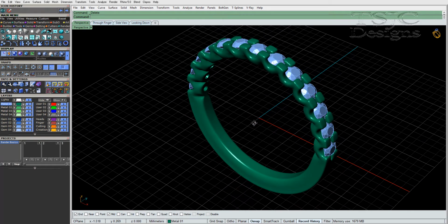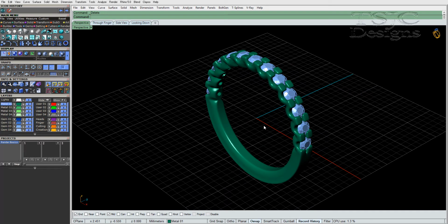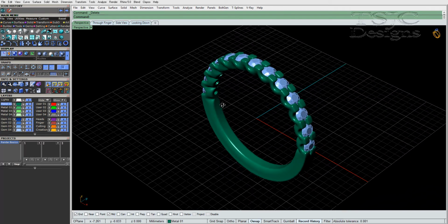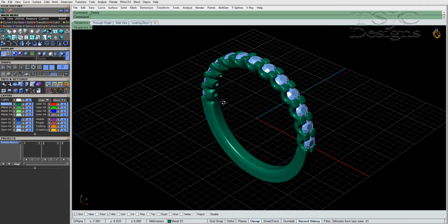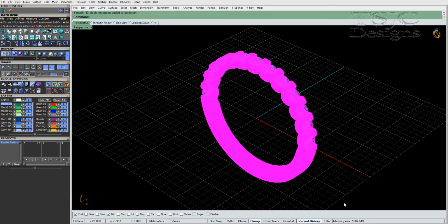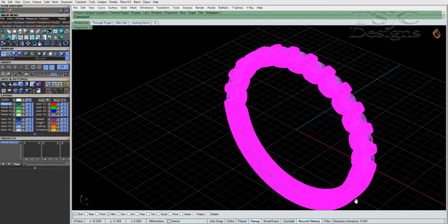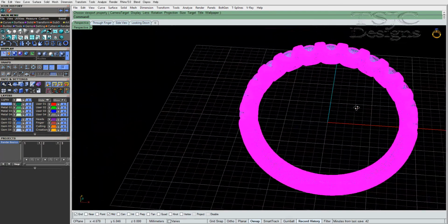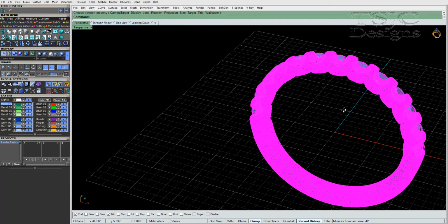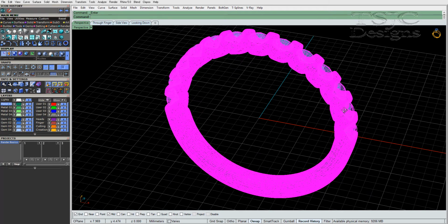So without further ado, let's have a look at placement first of your piece. To get continuity, what I prefer to do is highlight my model, press F3, which is zoom extent, and F5, which centers it. In some cases you've got this going on where it's going all over the place. So F5 centers your viewport, F3 does this.